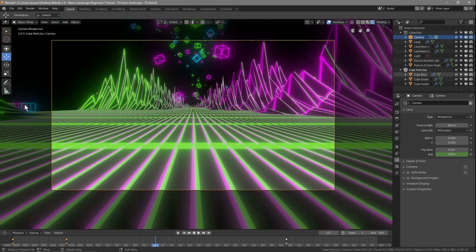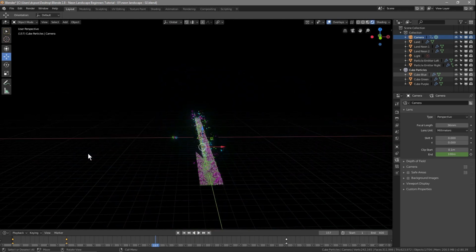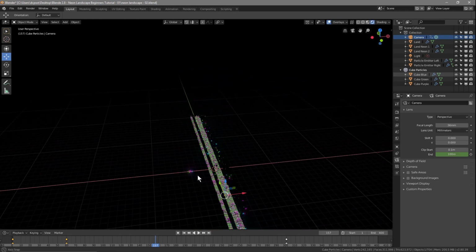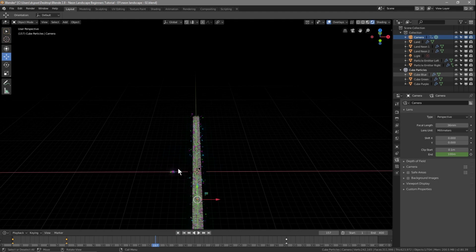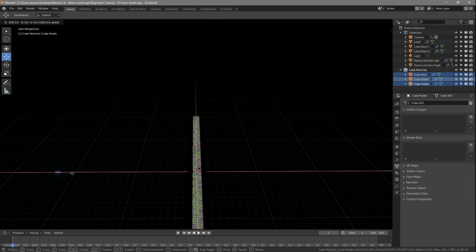So we need to get rid of these, right? Here, we're not getting rid of them, we need to move them. So let's middle mouse click and come up here somewhere. Let's find those objects. So we've got these 3 square cubes here. We can be a bit careful here what you're doing, right? Because you've got the camera selected. So move back to the first frame. Click on these 3. So click on the first cube and then shift click on these other 2 cubes here, and just drag them all the way out to the side here.